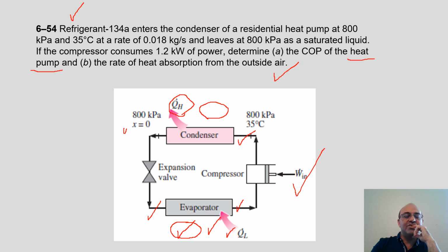Now you may ask, how do we do that? Do we need to turn the entire device around in the winter and summer? Well, you could do that, but usually the device has a switch, a kind of valve that can switch the direction of the refrigerant in the cycle.